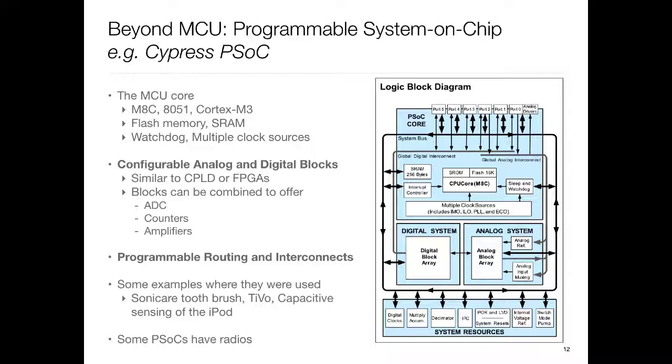These have the MCU, basically the CPU core, ROM, RAM, some peripherals, but they also have some FPGA and some programmable analog circuitry. On the analog side, they provide a whole bunch of op-amps and configurable structures, so the things you would need to do to hook up a sensor, like amplification, you can just implement out here. Not very high quality, but sufficient for a lot of applications: you just hook up your external sensors, and it takes care of all the stuff out there.